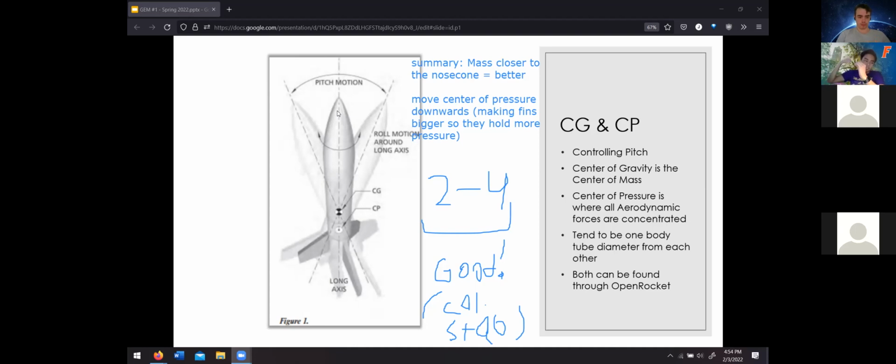The air doesn't have enough time to move around the rocket, which is why you have shock waves, because the air is moving too quickly. So it has to drastically change speed to get out of the way of the rocket. Once you start going at those speeds, the assumptions we make in the basic rocketry equations break down because they no longer fit. Going really fast will change the dynamics of the rocket, but it's not something we worry about because we're going much slower than those speeds.